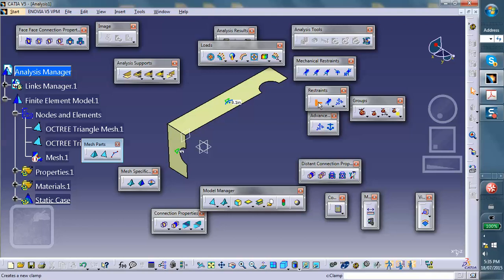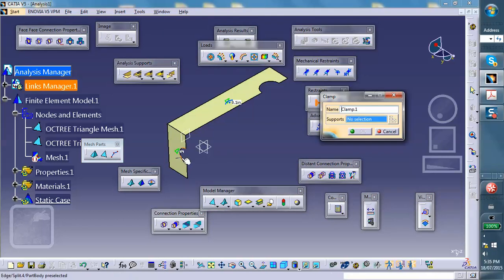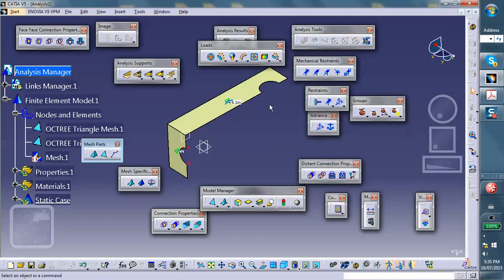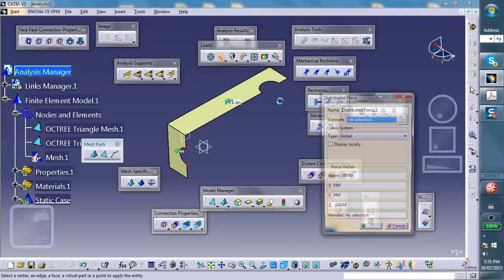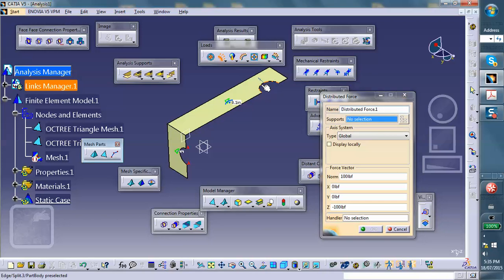We have that circuit half an arc is clamped. And I have a force of 100 pounds divided by 2. Remember, when it was the whole circle, I told you to put 100 pounds on it. Now, this is half a circle, so force on this face, on this edge, in the proper direction. Because of the way it did things, the direction has changed. So it's going to be minus 50, not 100. It's half of what you put on the actual model in the downward direction.